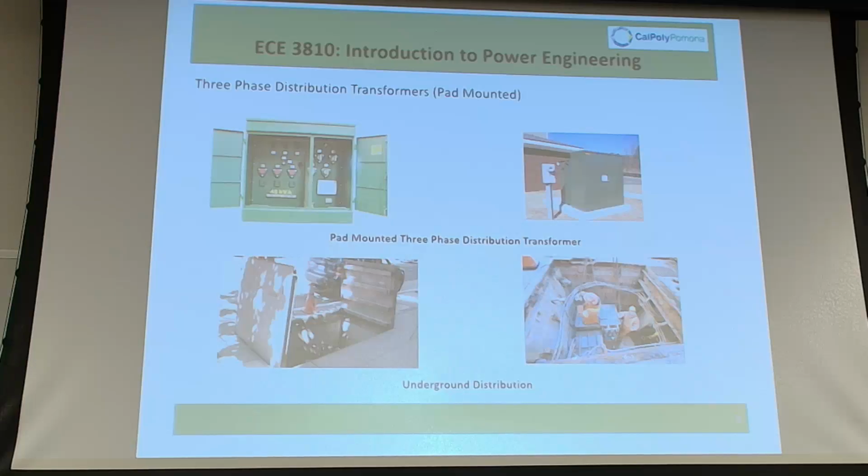Yeah. They're pretty big lines in comparison to the conductor that you see on the top for the same capacity, right? Because once again, if you have an overhead line, it's outside. You have all kinds of stuff there, like wind. They're out in the air, so it's easier to cool them off. When you bury the line, it's like you put something in a box. You gotta find a way to dissipate heat. So in order to dissipate heat, you just increase the size of the conductor. That's basically what it is. You gotta increase the surface area.